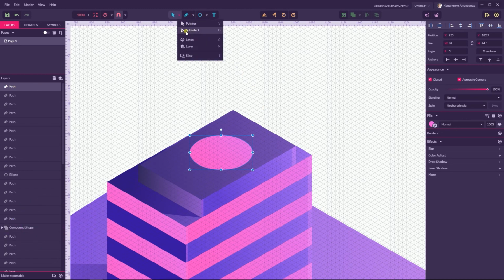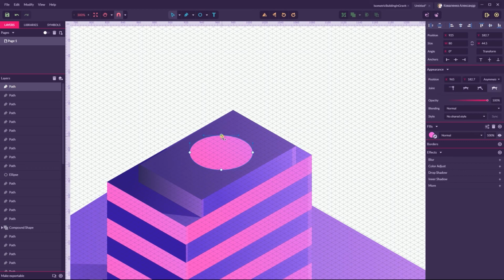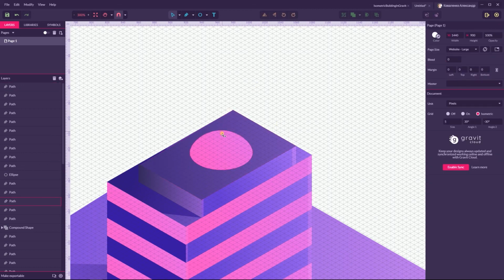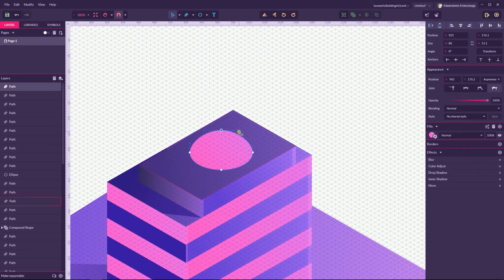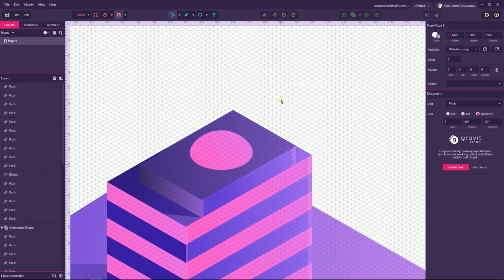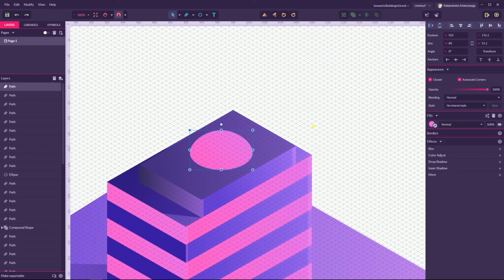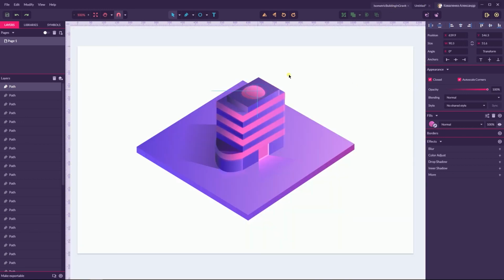we can simply grab this point with the Subselect tool and push it on the top, just like so. Or you can also push this on the bottom, so you can try a different adjustment, but I will just push one of the points to the top. Then grab these direction handles and maybe change some direction, but I don't want to bother with these small and fine details. Of course, you can add some of them yourself. You can make your own mind, of course.